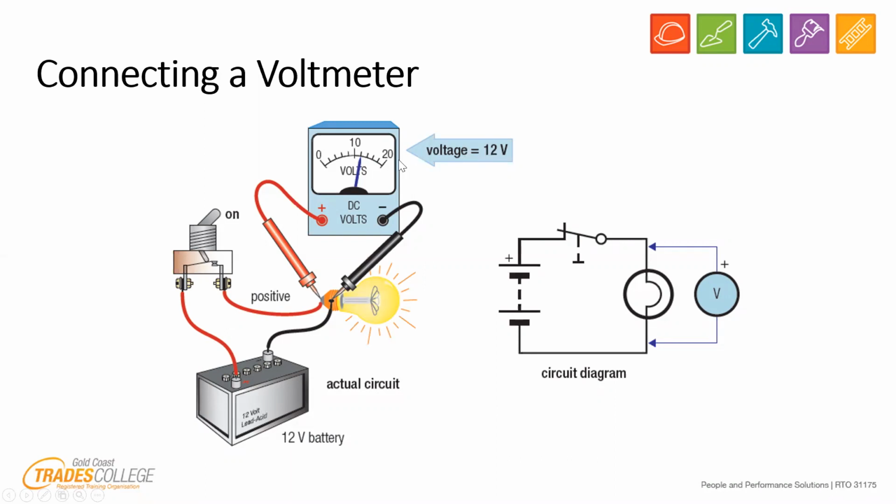When we're testing, guys, a tester is something which is always outside of a circuit, or we don't want the circuit to know we're testing it. Like we said when we were talking about measuring current, current has to flow through an ammeter. Now, for the circuit not to notice the ammeter's there, the ammeter must have an extremely low resistance, so the current can flow through it without noticing. The opposite is true for when we're measuring voltage.